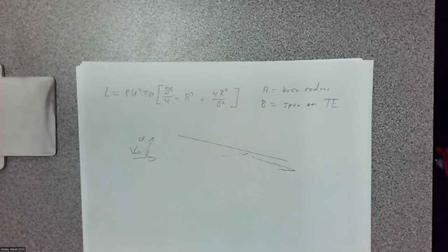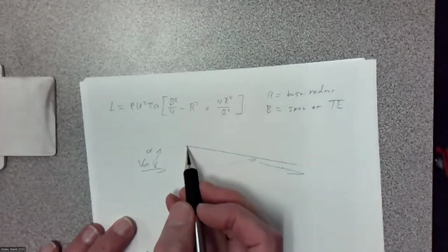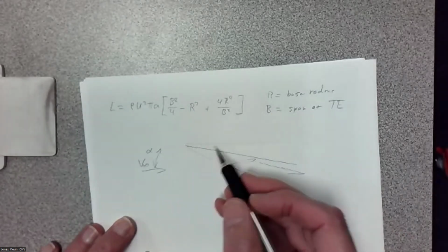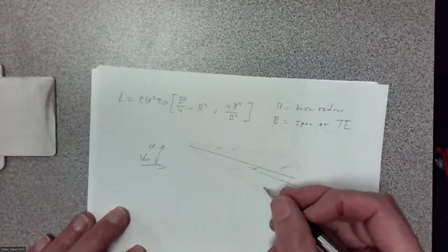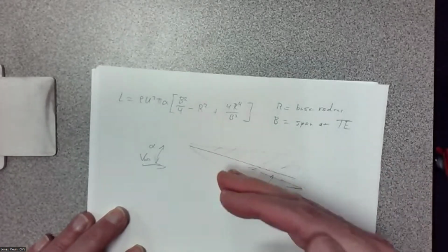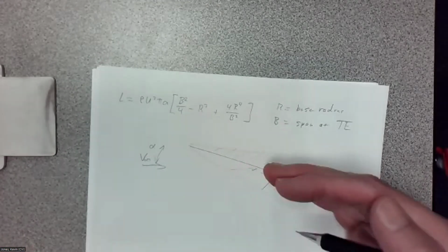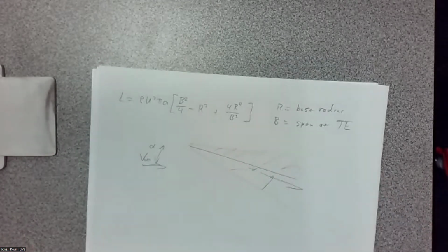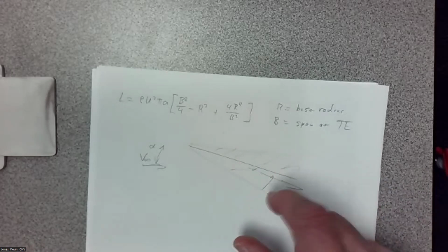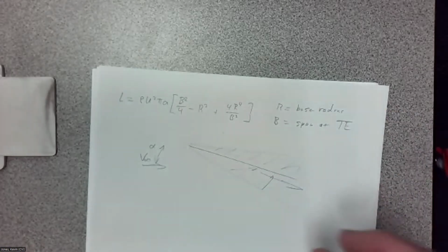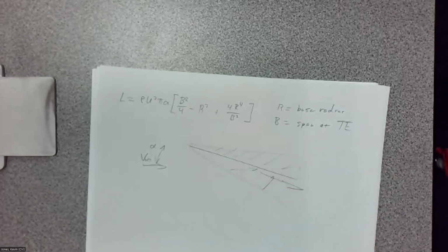Well, it turns out as the Mach number gets higher and higher, we have this shock wave out here, this wedge. But the higher the Mach number, the closer this gap is. So the turning point of the particles gets nearer and nearer to the surface. So sort of an asymptotic theory is, if the Mach number is high enough, particles get turned right at the surface and all of their momentum gets transferred to the body.